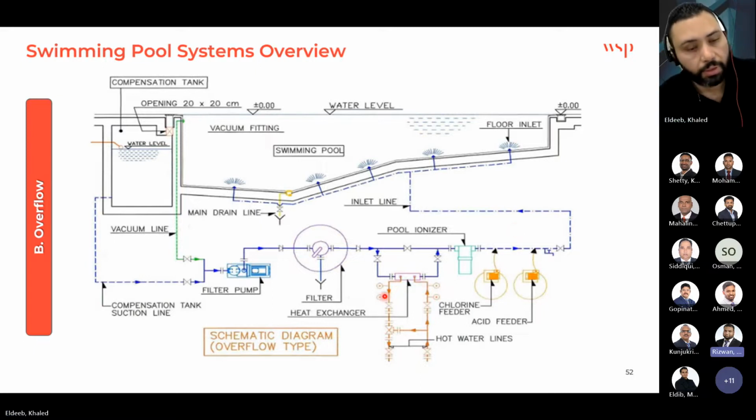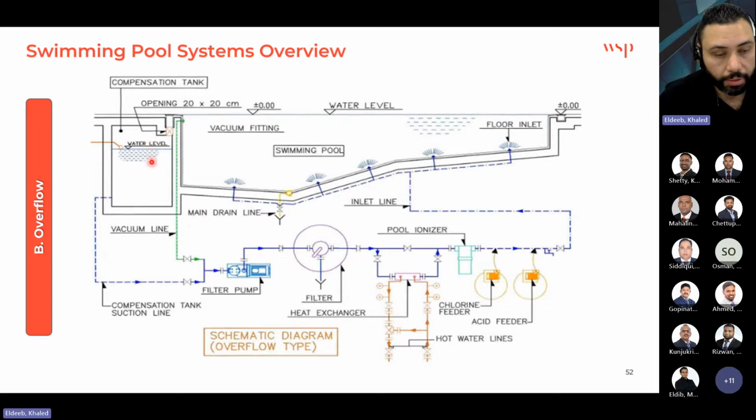My concern is that we have five water inlets and only one drain, and there is the tank without any drain arrangement. And how are we monitoring that compensation tank, whether it is interfaced with the pump? That part we need to look into.